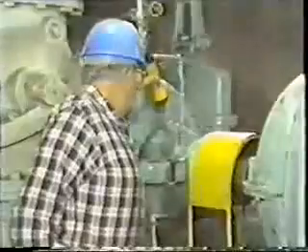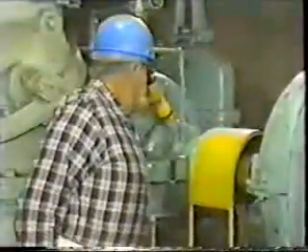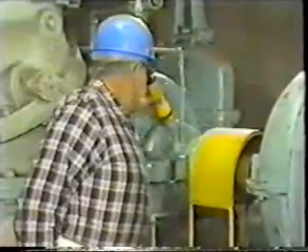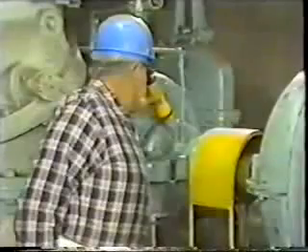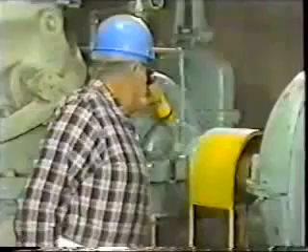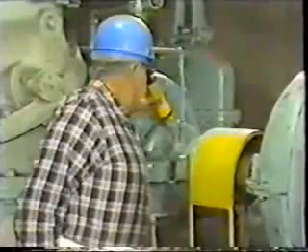leaking excessively. If the packing was leaking excessively on both ends of the pump, then it might indicate that there's been a change in the condition of the sealing water that has damaged the packing. On this pump, both ends would be equally affected by a change in sealing water, since both packing glands receive sealing water from the same source. So even though the operator said he hadn't noticed any problem on the inboard packing, it's important to verify that information. Gene finds that the runoff from the inboard packing looks normal.